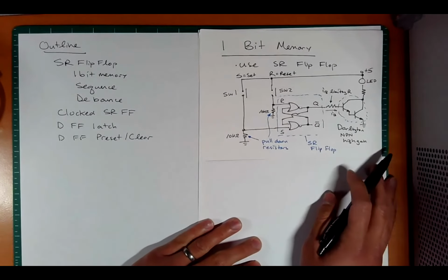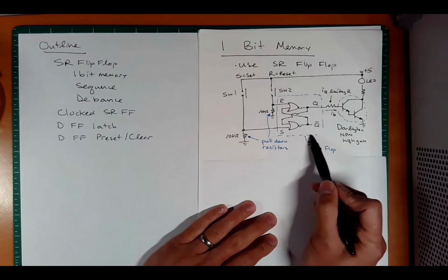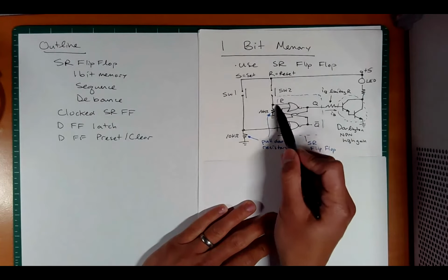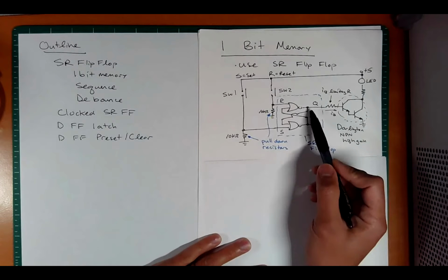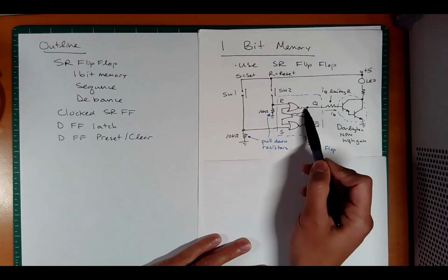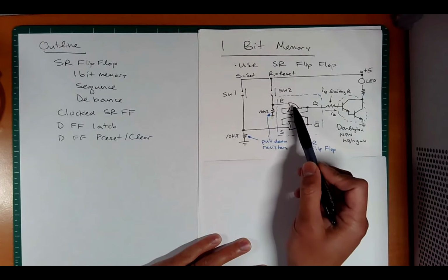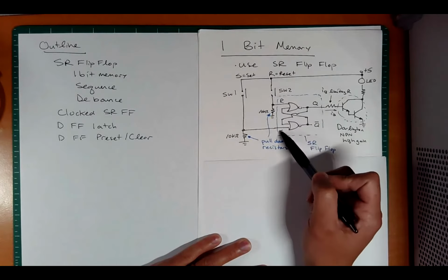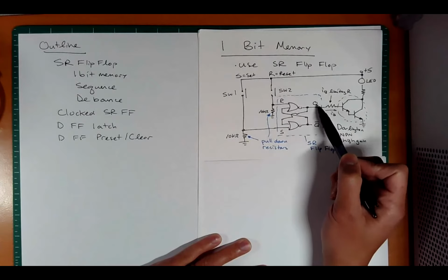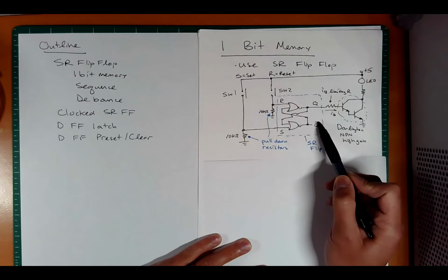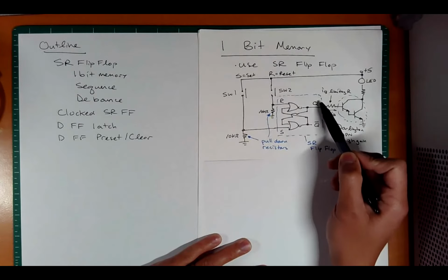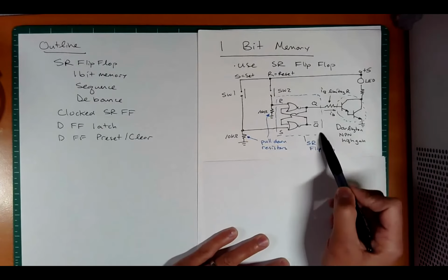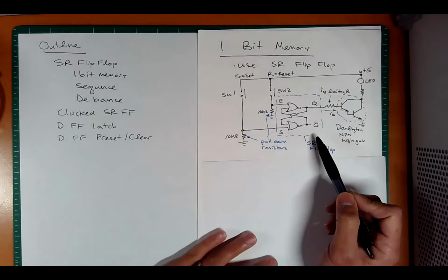I know this looks a little bit crazy, but this blue box here is where we have the set reset flip-flop. You can see the flip-flop nature because of this cross connection. Notice it's built with two NOR gates. We have the set and reset, and we have our output Q and Q bar. Remember, Q bar just means it's the opposite of Q. Okay, so let's see how this is attached to a circuit.